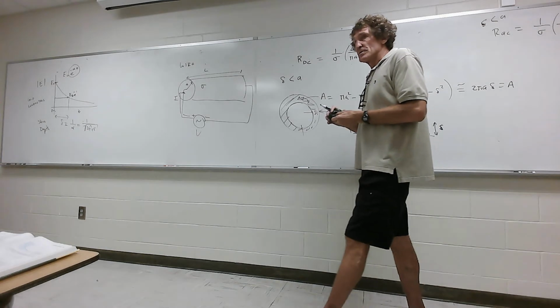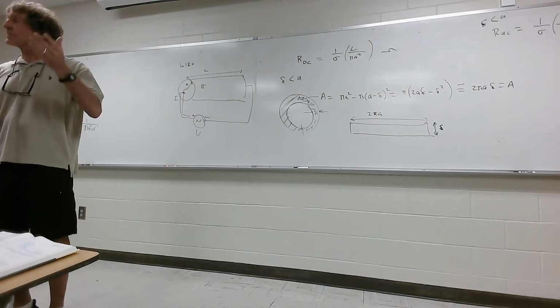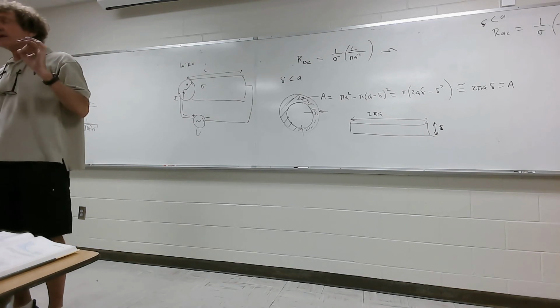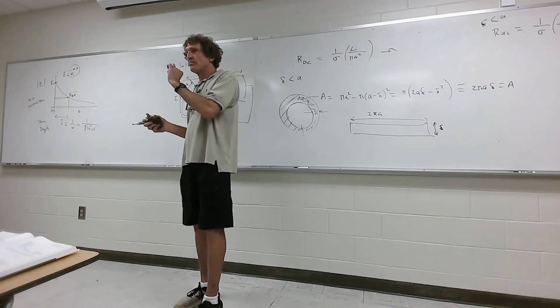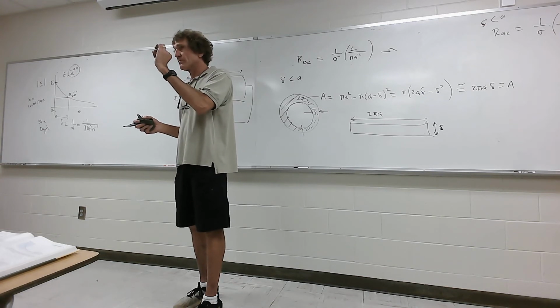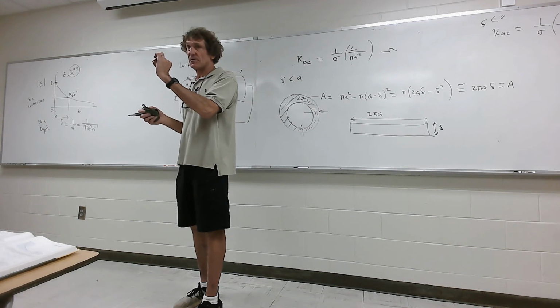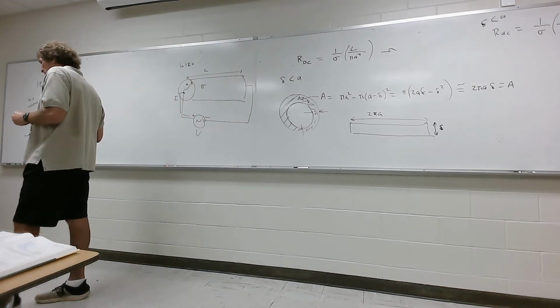And that resistance, as the skin depth goes down and down, smaller and smaller, goes up and up and up. And you can have a standard wire that may have tenths of an ohm per meter of resistance have all of a sudden 1,000 ohms of resistance at, say, gigahertz. Y'all follow me? That's why it's so important, especially in these high frequency applications.